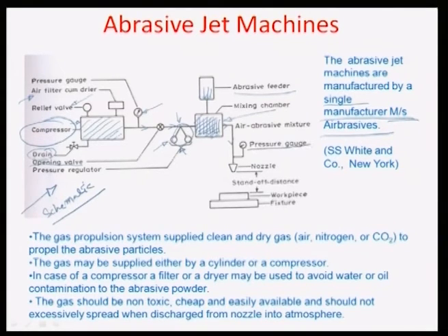There is again a pressure gauge which is very close to the tip to find out the pressure at which the abrasive would emanate from the nozzle, and this nozzle is at a certain standoff distance from the workpiece surface in consideration. The workpiece is duly fixed on a fixture so that it does not move, and it is capable of XYZ motion. Particularly in the microsystems fabrication case, you may have to design this fixture so that it can give you a good resolution in terms of movement of the various features above the nozzle.